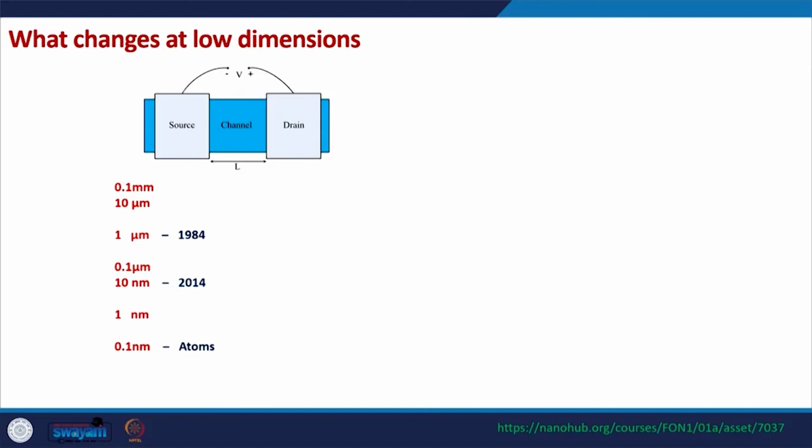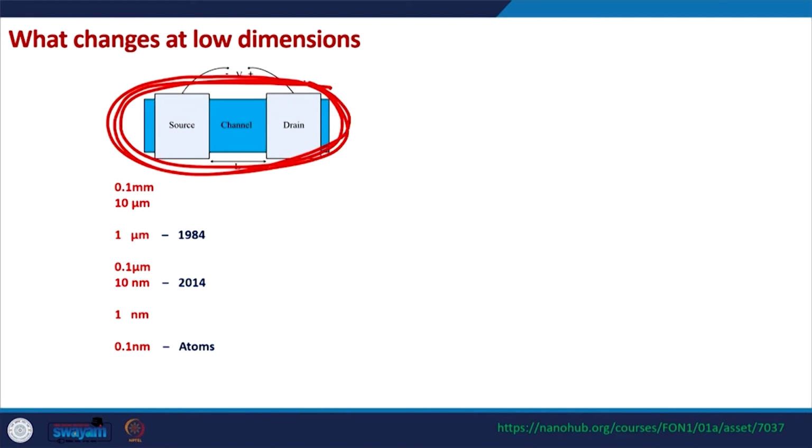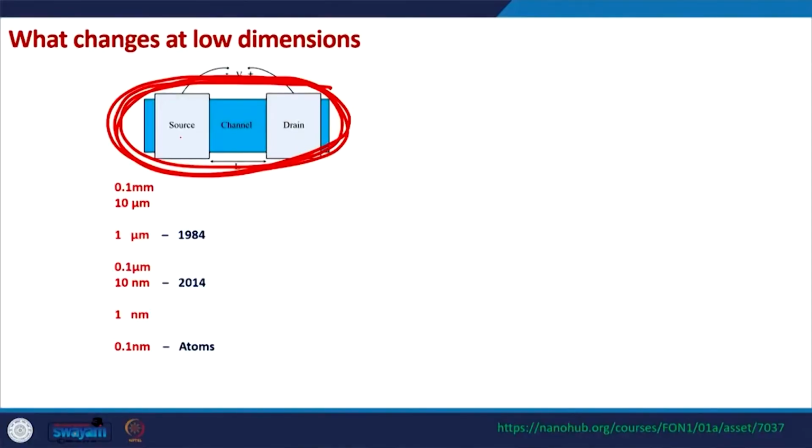Now let's for a moment just focus on this channel region of the device, this two terminal sub device in the MOSFET. Sub device means it is part of a bigger MOSFET, and we are just looking into the two terminal device, the device between the source and the drain and the channel region. And nowadays this channel region is extremely small, it is just tens of nanometers. In more technical terms it is known as the mesoscopic device.